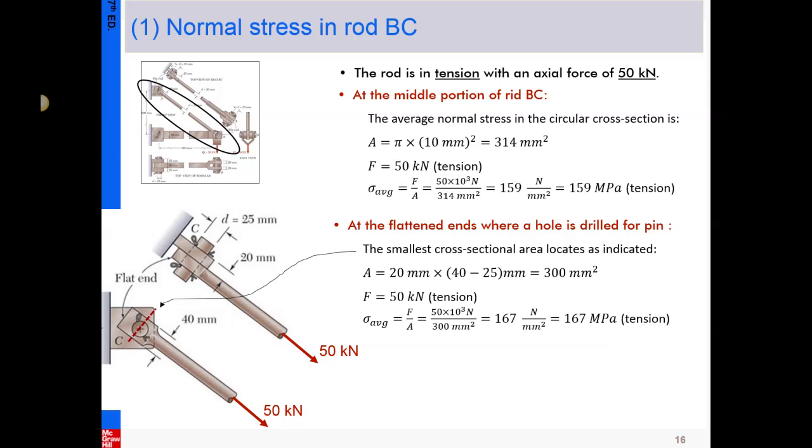The first exercise, we want to determine the stress in rod AB. So which means here I highlight, we want to determine what is the stress in the rod AB here. So in rod AB, we simply take a cross section anywhere, sometimes here. Okay, so that means here is a free body, the cross section we pick. Okay, and inherited from 2 slides before, we know the magnitude of the force in AB is 50, and we know it is in tension.